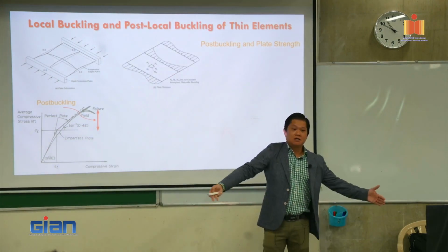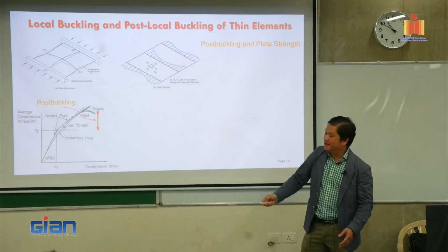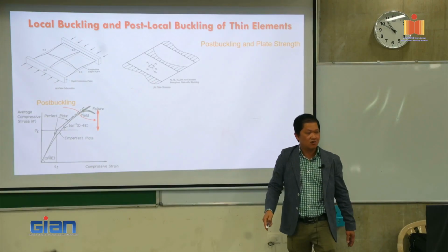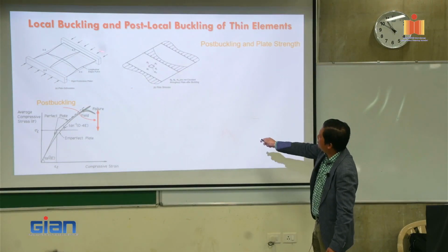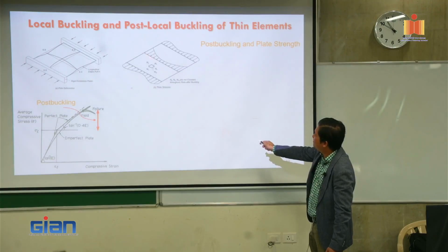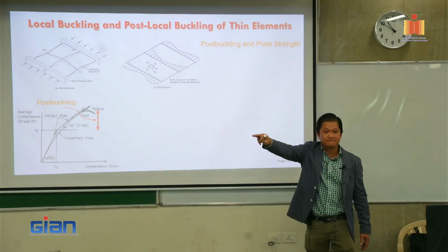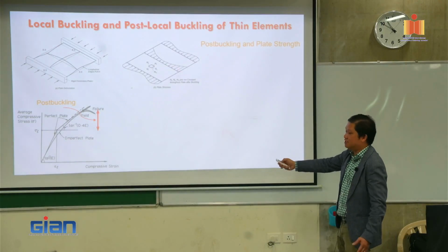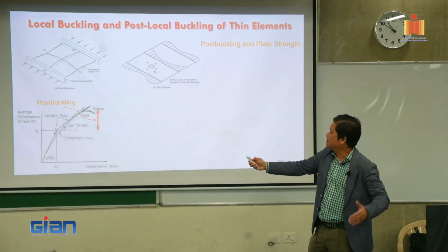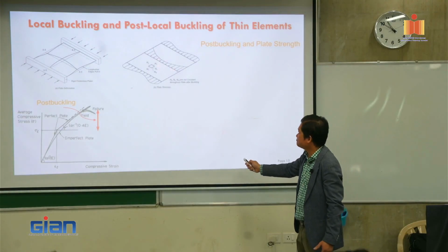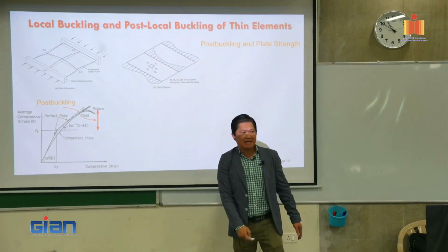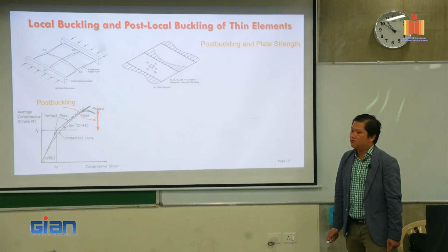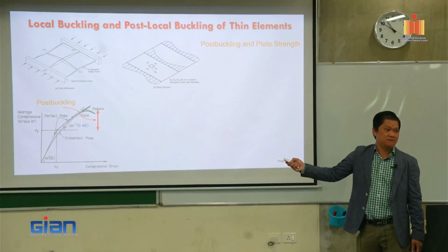The stress at the end is a little bit complicated. It's not constant, and when you cut in the middle of the plate, you can see that it's a really non-constant stress distribution. The stress at the edge tends to increase, and the middle is going down. So this is complicated: how to design for that, how to calculate the sigma critical for those stress distributions.